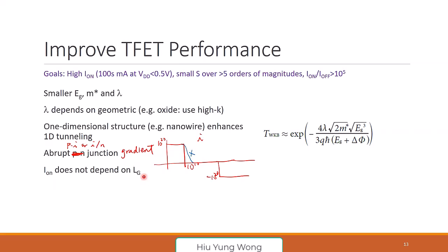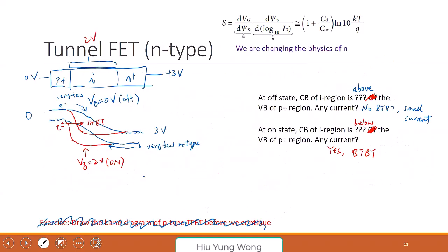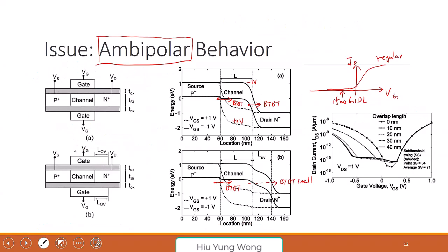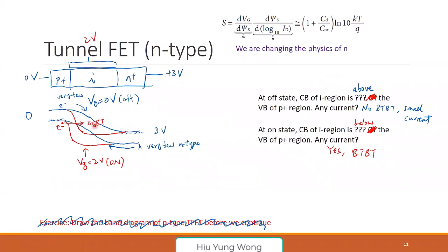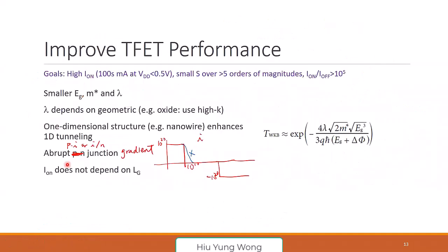So after all, for tunnel FET, what I want you to know is the mechanism. You understand that you apply a high bias, and suddenly you turn on the band-to-band tunneling by applying a gate bias, making the barrier very narrow. And it has a bipolar behavior. And whatever can change the band-to-band tunneling can be used to optimize the tunnel FET. That's the focus.